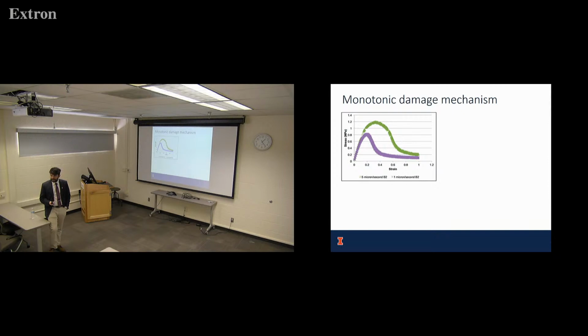In terms of shape and size of cavity, I would say that's most dependent on base binder more than aging condition or loading rate or anything. But in terms of formation of cavities, yeah, because the stress strain curve changes a lot. So we do see that. And we've actually seen some binders where the stress strain curve gets to peak and it's basically a flat line from peak down. Like it's almost zero post-peak deformation. So we do see a lot of strange things, and a lot of it is adhesion issues in those aged